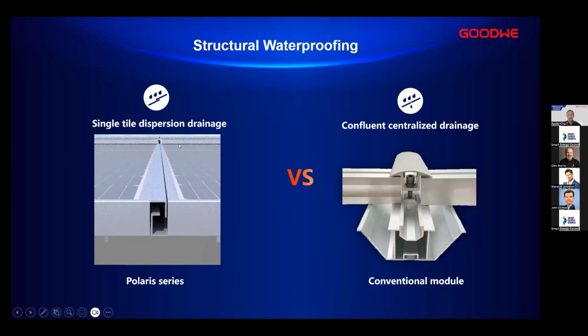But for our products, as you can see, it's a two-shaped design. In that case, even if water goes inside the seam, it goes to the chamber. And thanks to this towel-type installation, each panel steps on the other. So the water that comes from the top of the panel will drop to the second layer of the panel, all the way down to the bottom.